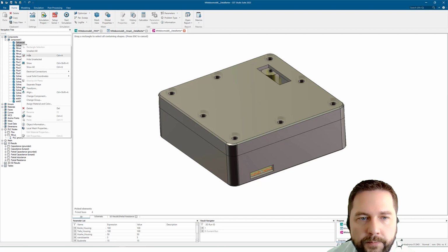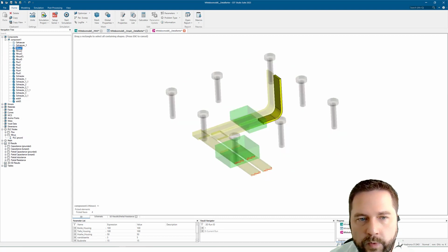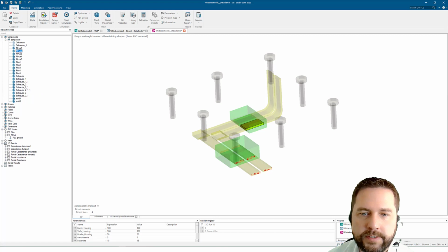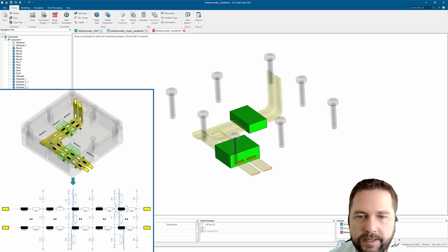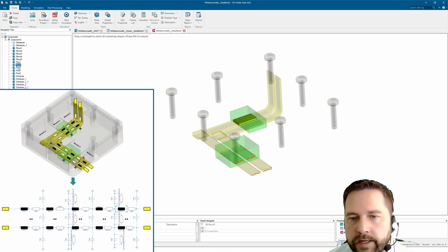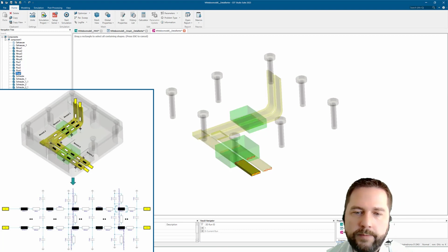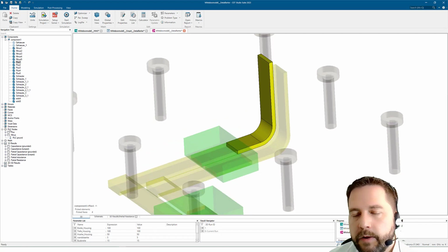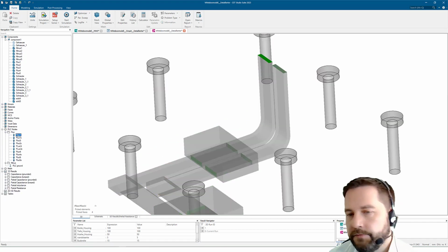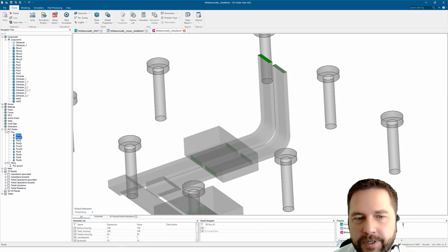The other parts, the minus and the plus bus bars, we divided into several sections, as you see here, in those sections where we expect a different behavior concerning the parasitic capacitances. So the area with dielectrics we cut out, the areas without dielectrics we cut out, and then we are able to calculate them separately. Because this partial RLC solver is really able to calculate partial inductances, which is not physical, but which helps us to put some values into our circuit model.